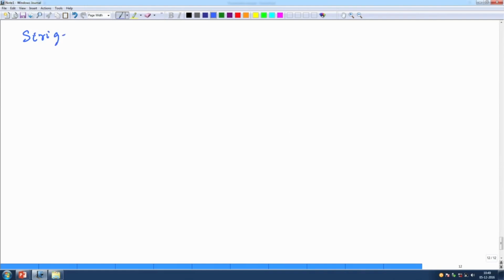So, welcome to today's lecture. In the last class we mentioned what the modified Nusselt number and Sherwood number are in this particular case. Now let us look at the form of this f, which we already mentioned in the previous lectures. Here we will once again, for the sake of completeness, reiterate that. This is Abramzon and Sirignano's model essentially.